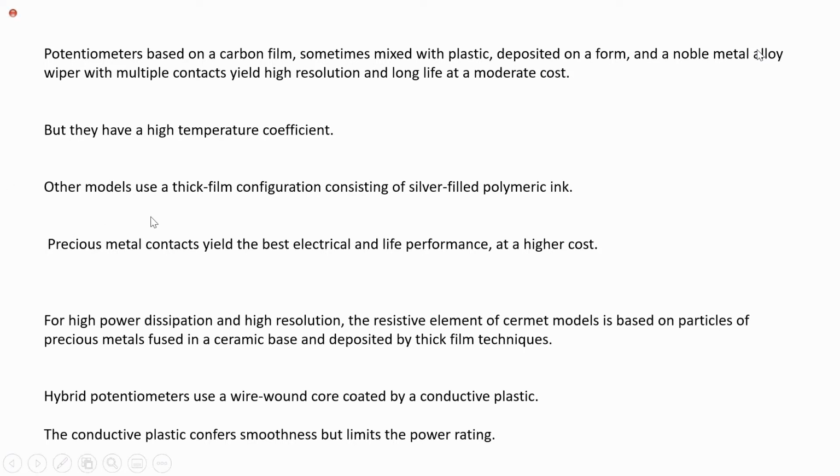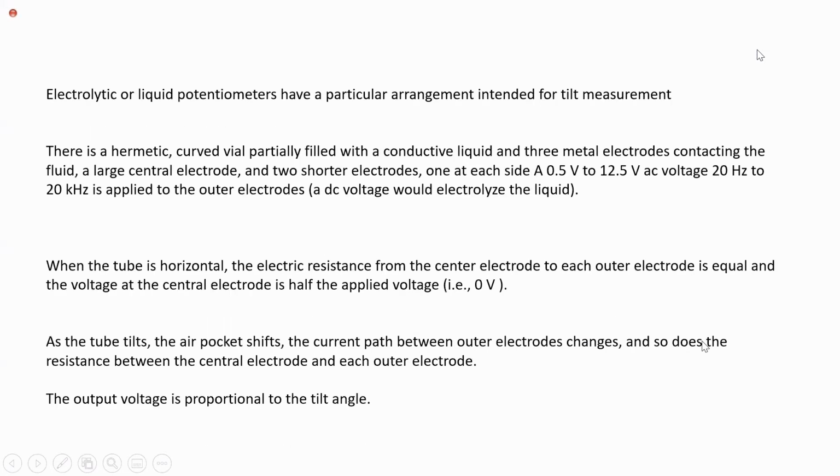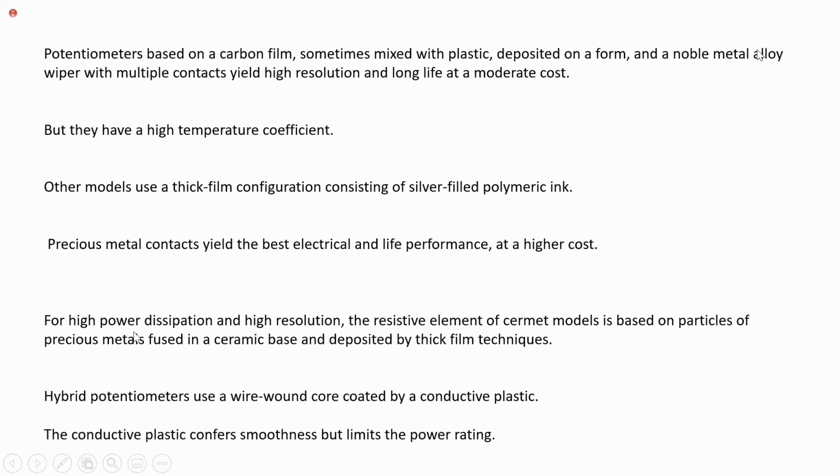Other models use a thick film configuration consisting of silver filled polymeric ink. Precious metal contacts yield the best electrical and life performance at a higher cost. For high power dissipation and high resolution, the resistive element is cermet. Cermet is one kind of ceramic material, students. The resistive element of cermet models is based on particles of precious metals fused in a ceramic base and deposited by thick film techniques.